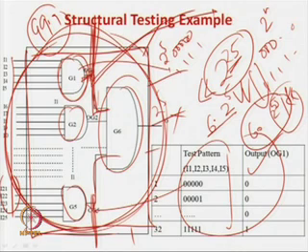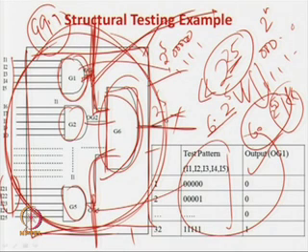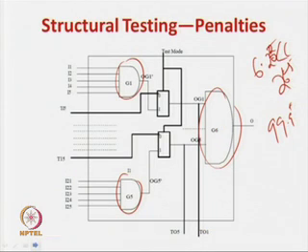Secondly, if you have to test this last AND gate, the output can be observed because this is directly coming out of the circuit. But now see, again these inputs to this AND gate are not directly controllable, because they are being fed by these 5 AND gates. This gate is feeding this gate. So you cannot directly control this. So for that you have to make a very different arrangement. So we will just see.